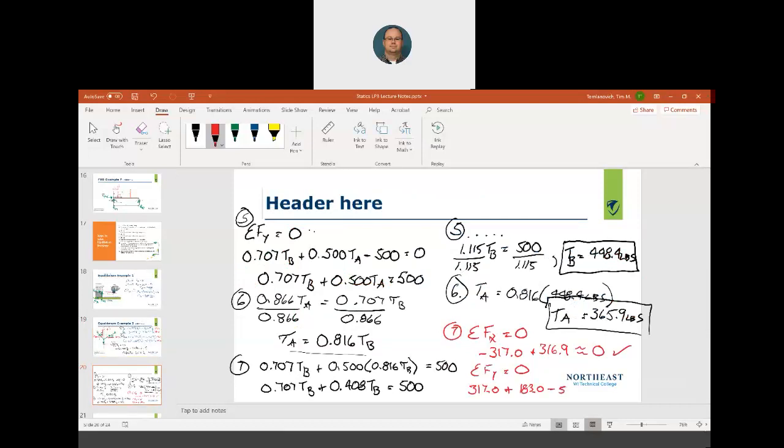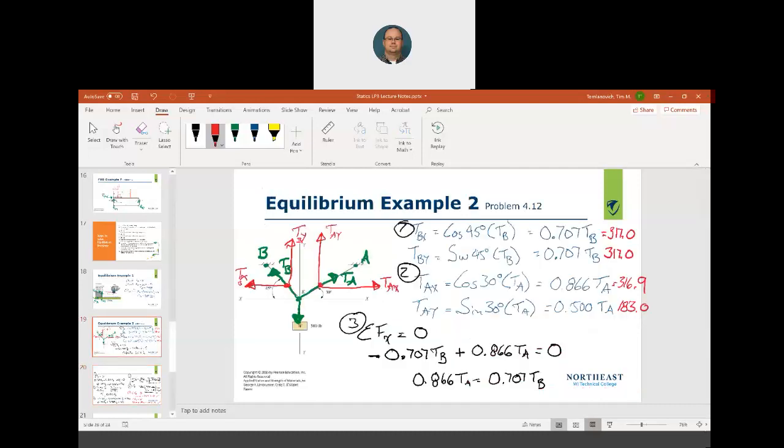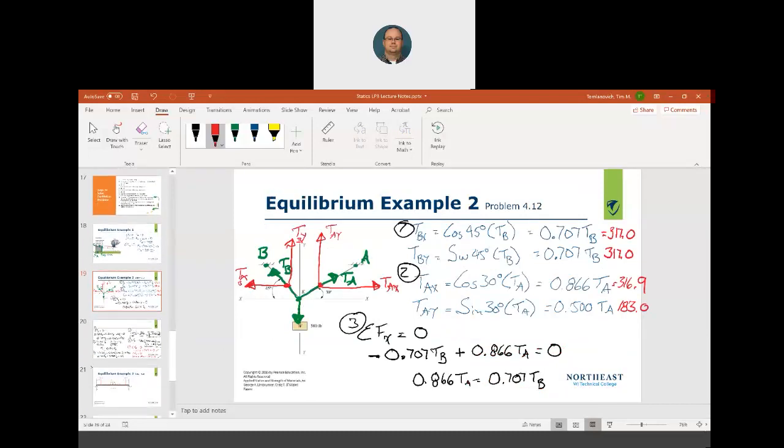Minus the 500-pound weight. And that should approximately equal 0. And let's hope it is. 317 plus 183 exactly equals 500. So I know I did my numbers right. So there is the tension in my cable. So I just solved this guy. Holy moly, huh? All right.